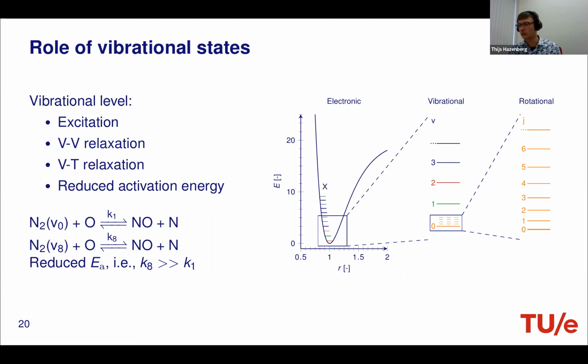Generally, in plasma-assisted combustion, starting to populate nitrogen vibrational levels is something that you do not want. Why? Because you're storing energy in vibrational levels. This energy is not available in terms of kinetic gas energy, so it doesn't provide a temperature increase in the gas. What it will provide is an acceleration in the Zeldovich mechanism, and thus produce extra nitrogen oxide.